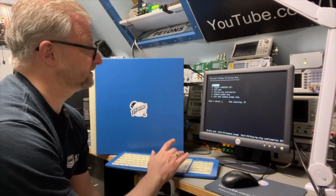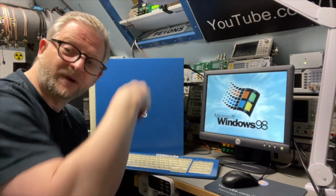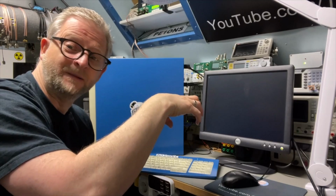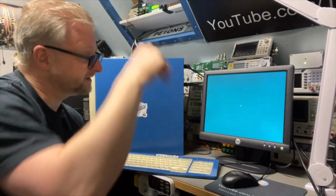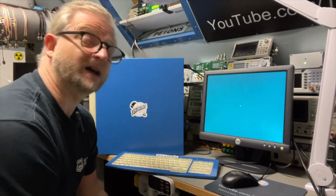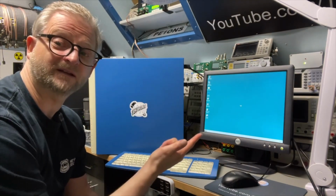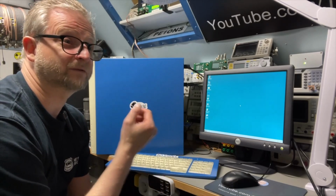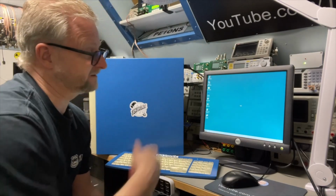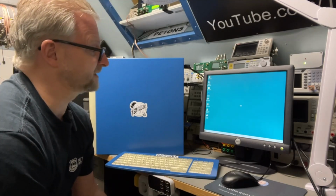Boot normal, not in DOS mode. So I will leave the links also to all those VISA drivers, because most of the programs don't talk directly to the GPIB. It goes through this VISA layer, and then you have some sort of compatibility layer, and then you can talk through your GPIB to the device. And I found different VISA drivers for Windows 95, even 98, I think Millennium Edition, for 2K, and XP, and of course for Windows 10 is the latest. You can just download directly from National Instruments, and I will show you that on my laptop and on the newer PC.